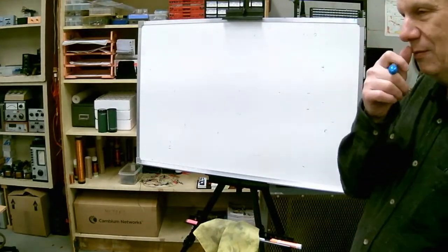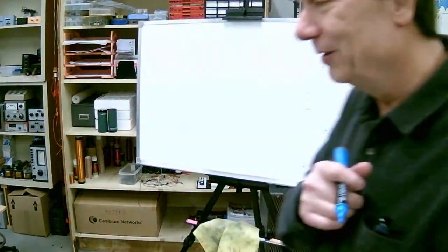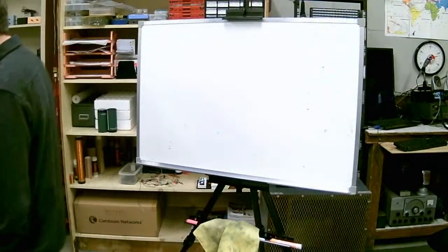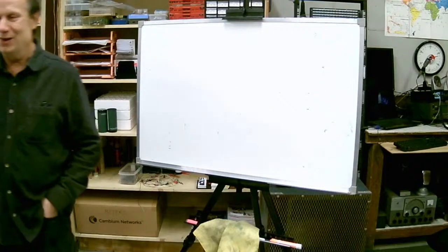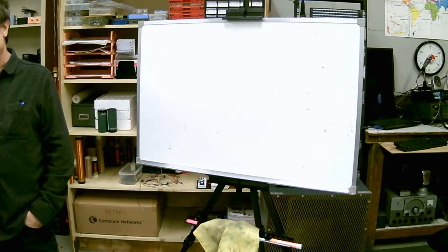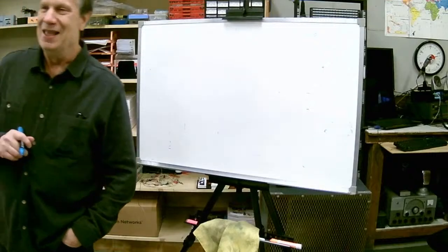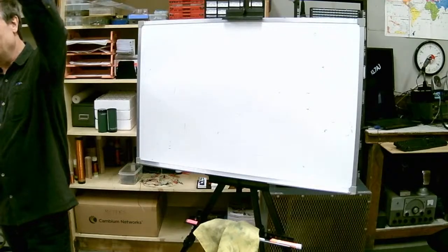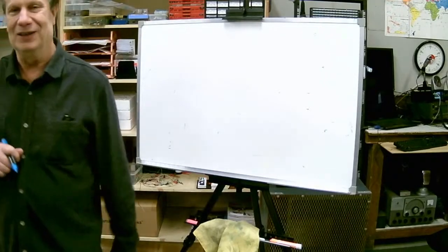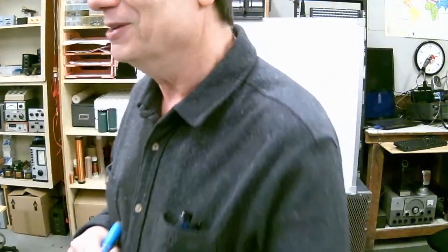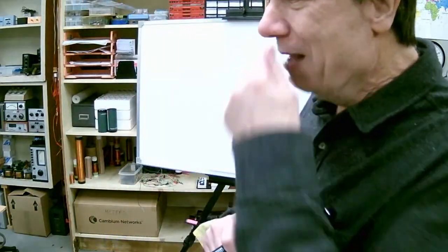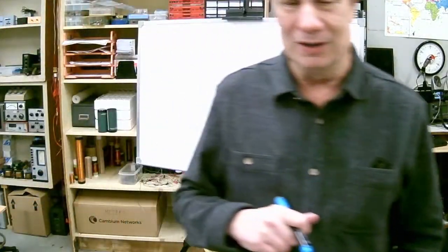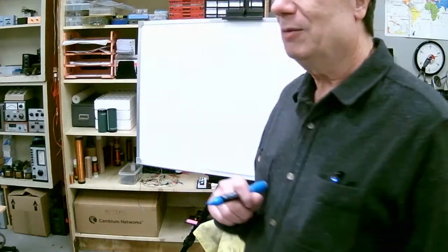Okay, so what do we do with the signal once we receive it? Do we have to amplify it somehow? Now, you don't have to. With a crystal radio, if you have a really strong signal, all you need is a headphone and a diode. That's assuming the signal is very strong. We've got a 970 station right down the road here, and you can pick that up pretty easily with a diode and a headphone. But let's talk about more refined radios and what we need to do to receive a signal. Let's talk about some actual power levels.